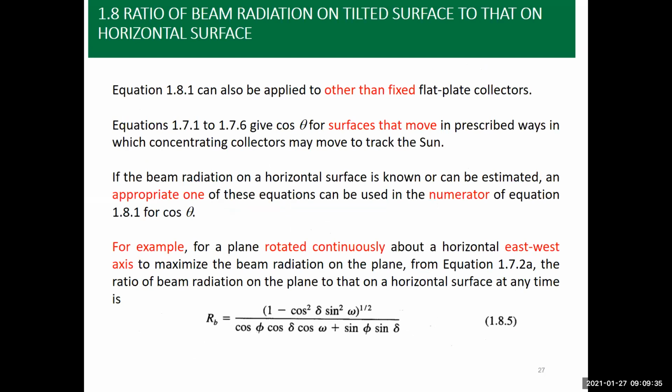The equations that we have can be used not necessarily for a fixed surface. Remember, we said that the general expression that I started with today was for calculating theta for a fixed surface. However, it doesn't have to be fixed. It can be rotating on a horizontal east-west axis, or a horizontal north-south axis, or a vertical axis, or an axis which is parallel to the axis of rotation of the Earth.